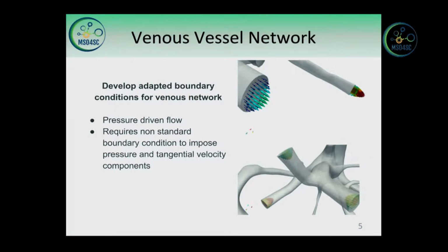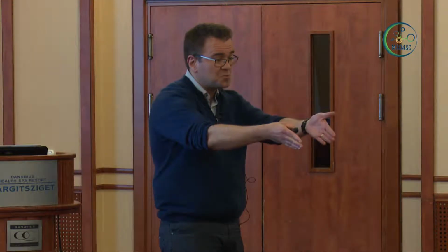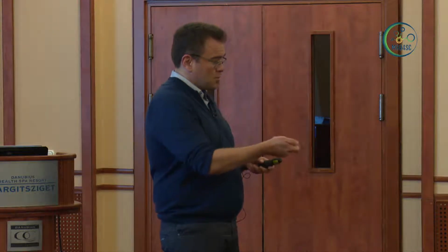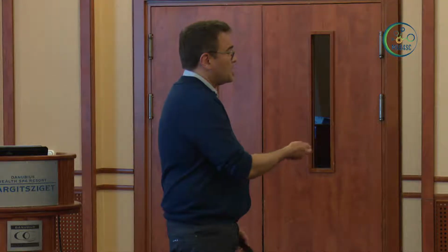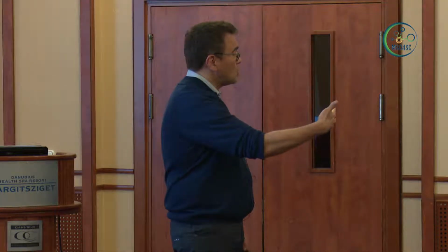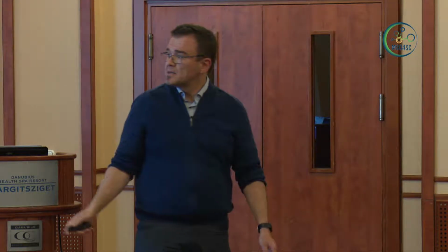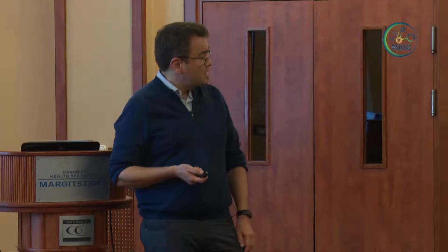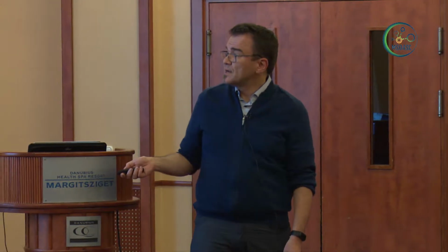And it models also nicely the fact that the tube, we cut the tube, but the tube continues, right? So if you use a standard outlet boundary condition, you will get a wrong outflow condition typically. So we did this if you are interested, and it's also, of course, delivered with the CFD toolbox that we provide here.